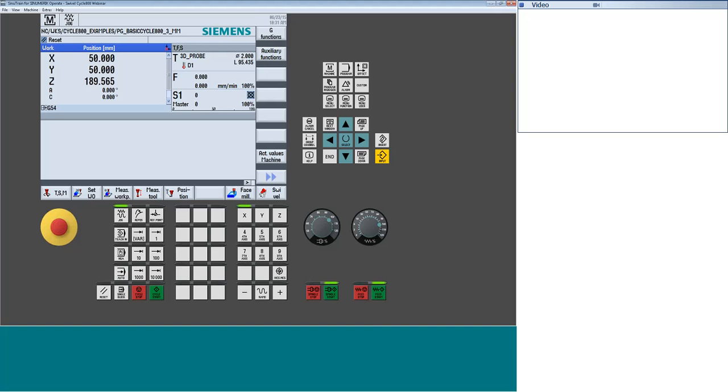So one of the first things we mentioned is, how do I move a machine around the 5-axis world manually? More importantly, where am I looking for the information as I do move it around? So in our upper left-hand corner, we have the work field. And the work field right here, you can see here, this is your axis display, it's your feedback display. So right now it's sitting on work because the work coordinate system is being represented.